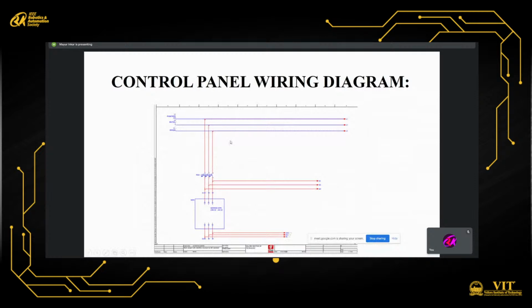You will give these notations in the file. And this is the electrical device, how it is connected through the MCB in between. Now through the MCB, these three connections are going away, and as you can see, there is a numbering to these wires, which is W1, W2, W3.